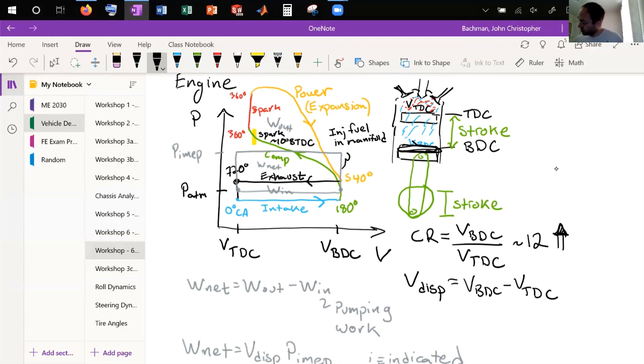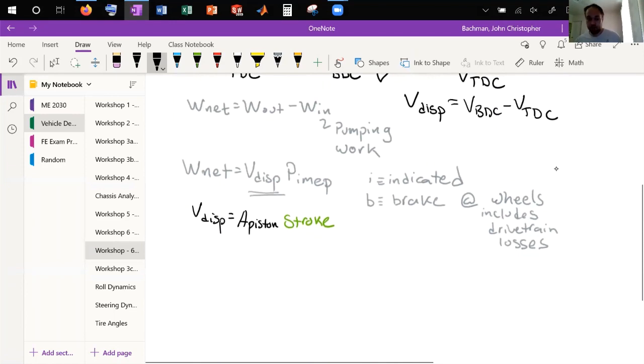And then of course they'll do different shapes on the top, right? Sometimes there'll be a hemispherical top, so that way you can decrease your volume at top dead center because it can get more up into that area. And then usually you'll also have little indentations for where your valves come in, because when it goes to top dead center, sometimes your valves might not be completely closed. For example, after the exhaust phase, you might have some valve overlap, and we talked more about that last time.